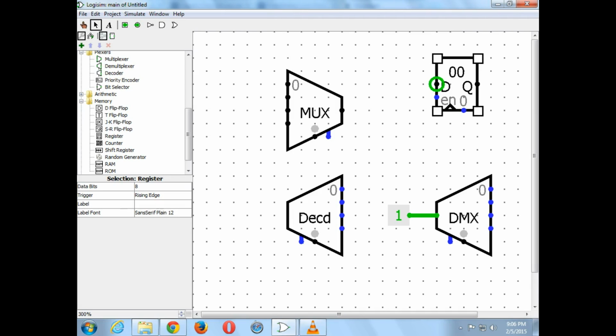If you want to change the content of a register, you first present the bit pattern to the input, which is called the data port. So you specify, like 00101111, whatever you want, to the data port, but it's not paying attention because the enable pin, which is this pin here, needs to be a 1 in order for the register to pay any attention to the D port or the clock line, which is the wedge thing.